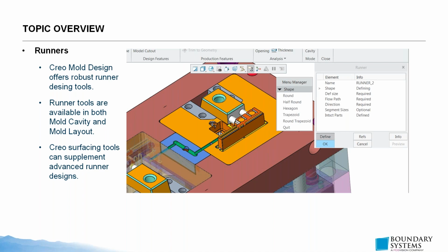You get to break a couple of rules in Sketch, if you will, when you make water lines inside of mold that you wouldn't typically otherwise get to break in a Creo extrude feature on the parametric side, if you will. So the tools, while they utilize conventional, familiar Creo functional workflows like the Sketcher, are additionally optimized to speak to the needs of mold, things like I mentioned, overlapping sketches, things to that effect.